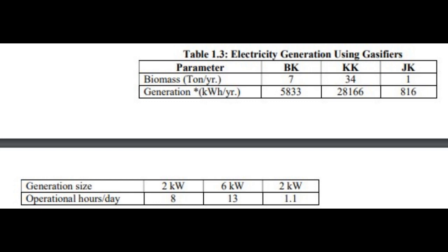Case 1. Demand to be met by PV system alone. 1. Monthly generation of electricity from a PV panel of 1 square m area is evaluated using the data on solar radiation and ambient temperature. 2. The PV area required to meet the maximum demand, shown in Table 1.2, is evaluated, and then using this area, the generation for each month is evaluated. 3. The battery size corresponds to the lighting load only. 4. Total life cycle cost of the system is evaluated.